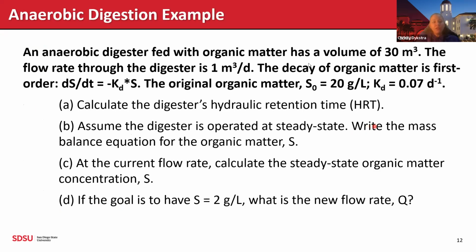All right, so here is an anaerobic digestion problem. And so a couple of things here, if you're not familiar with this terminology, first we want to calculate this hydraulic retention time. And this is considered how long one molecule of water will stay inside the digester.